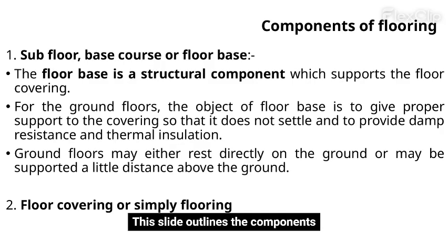This slide outlines the components of flooring. The main components are the subfloor, or base course, and the floor covering. The subfloor provides structural support and may offer damp resistance and thermal insulation. The floor covering is the visible, finished surface.